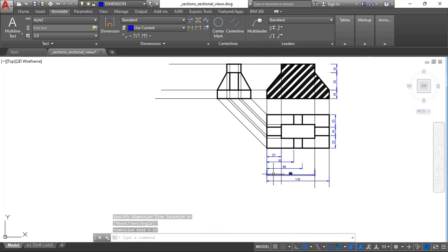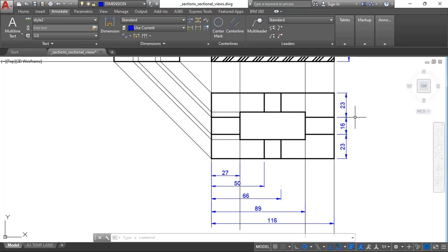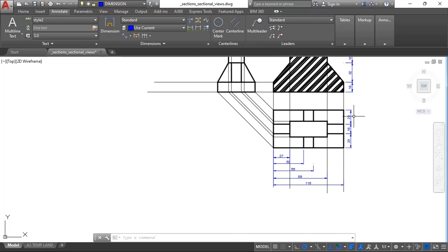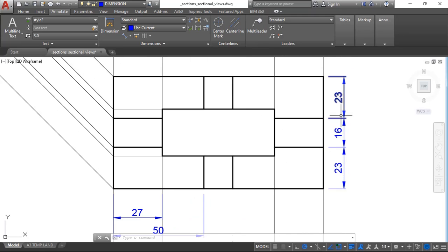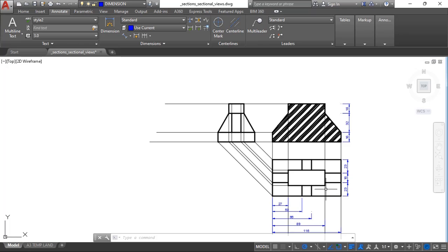Okay, so this is the progressive arrangement. Remember those dimensioning arrangements. So this is progressive. Start off with the smallest, then the biggest, like that. This is chain. If they're in line like this, then this is chain. Something here, chain. And what else do we need?